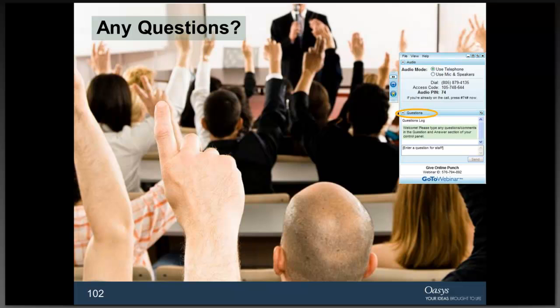Steve? Sorry, I think you're muted. Can you hear me? I can hear you now. I think you were muted before. Okay, I'll start again. Yes, you do still need to have elements around to define the edges. So you can't omit one edge and then have that one not loaded. The way to accommodate that sort of thing is to put dummy elements around edges which you're not particularly interested in.